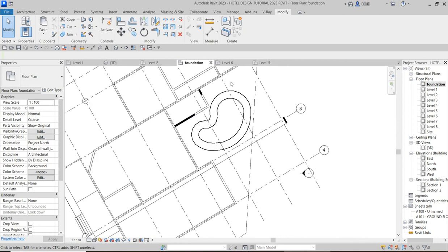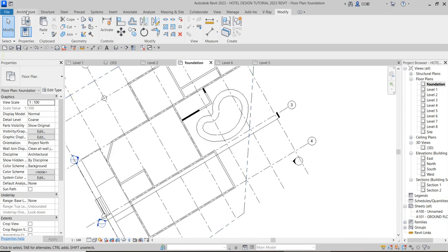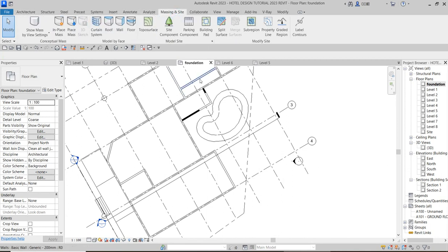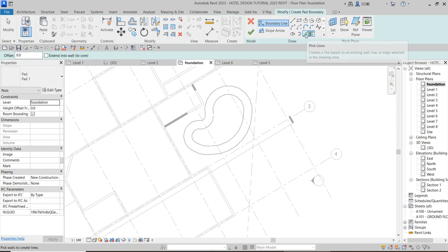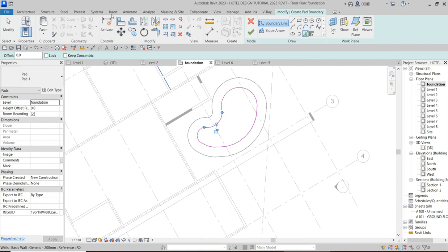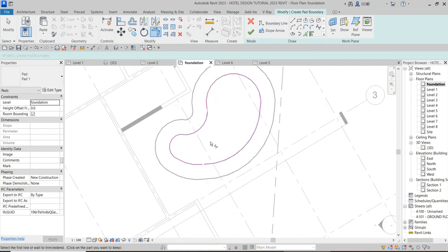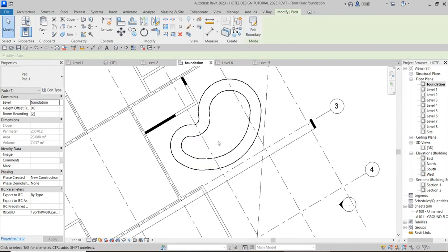So now we want to create a pad. So how do you do that? You go to your maintenance site. At the maintenance site, you say building pad. Building pad here will allow you to create a hole in that topo surface. And this is the part in which you want to create a swimming pool. So here you align them, make sure that they are all close in tight. So that is what you have created and say okay.